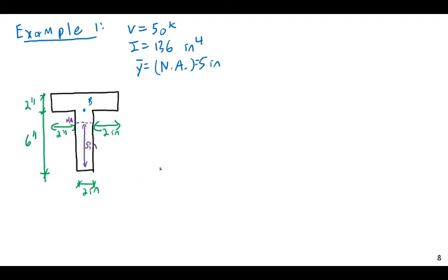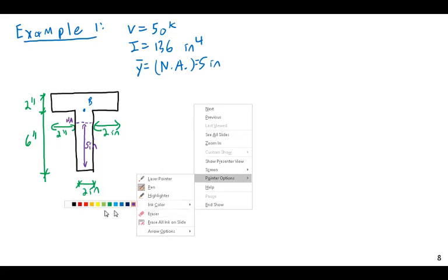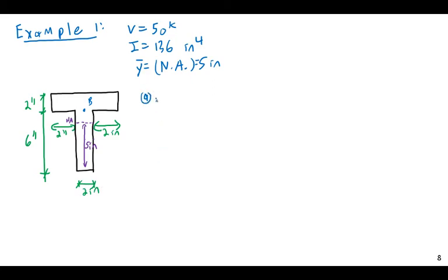Here. Okay, so I'm going to have a series of prompts, and I'm going to go through them. Basically, I'm going to have 2 parts. In the first one, they're essentially the same as the previous problem, but we're just going to learn how to work with this for non-symmetric sections. That's what I wanted to say. Okay, so part A, let us get the shear stress at the neutral axis.